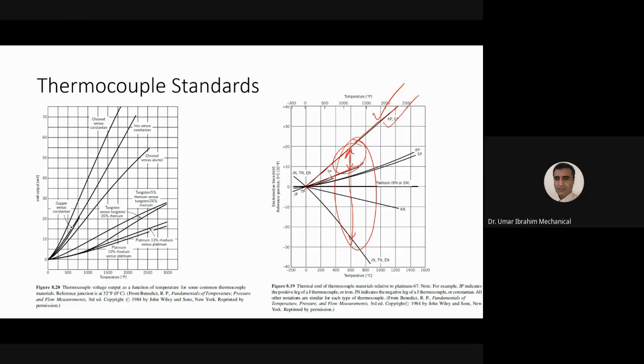And this material will, for the temperature difference of junction, contribute negative potential. So the potential difference between the positive contributing material and negative contributing material will be the output of the thermocouple. सही है सर। ठीक है,